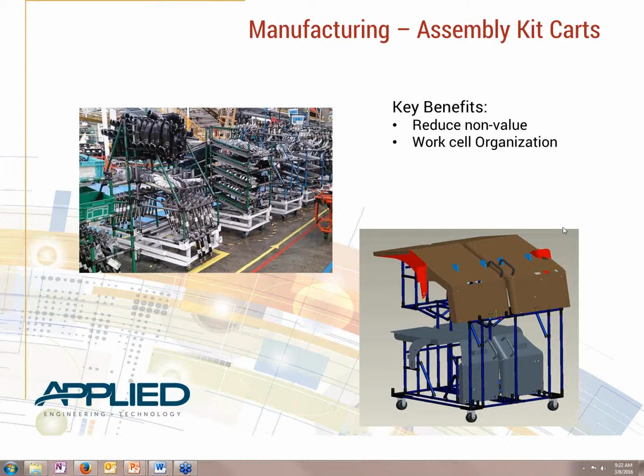So you're not worrying about this person bending over here to grab these parts and hurting their back. You can have it all loaded up at an acceptable level. It's very visual, so you can see, yep, I've got enough parts for 2 more assemblies here, or whatever it happens to be. So that's a huge thing, and you can build those carts, real simple carts, with all the larger parts and smaller parts hung and stacked on there. So it really works out slick.